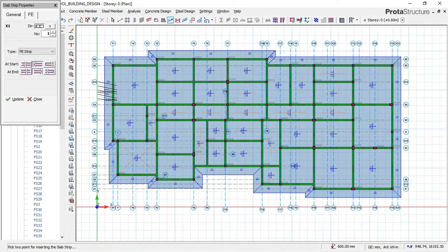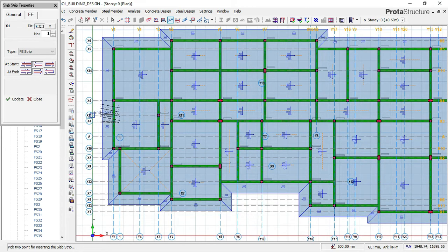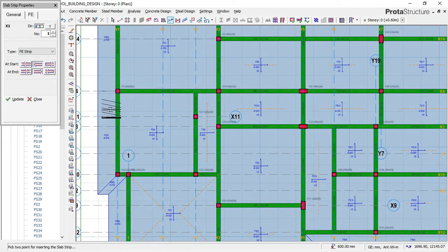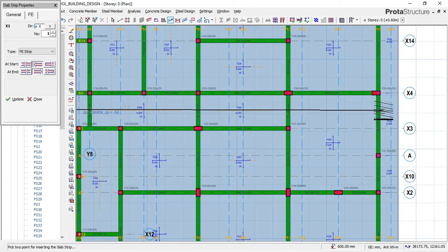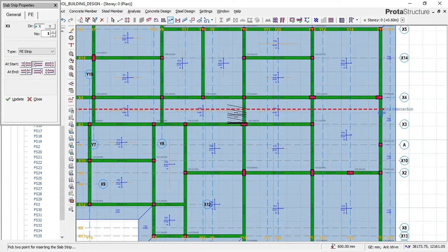Now since this toe reinforcement is not the same thing as this slab raft reinforcement, and since they are at the same level, that means they will not detail the two together. So I'll have to start my cuttings of the slab detailing from this point and not at this edge here. So I'll quickly start from the very point once I pass the slab, this beam here. So I'll click at this point and then go over to the next point since I'm cutting X direction, and then hold my control key to make my line straight, and then click at this point here. Okay, so right now I have cut my X direction.